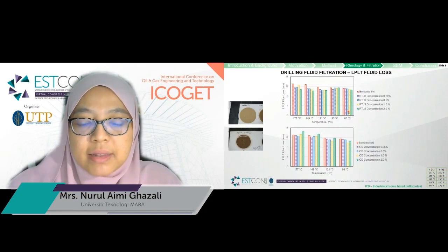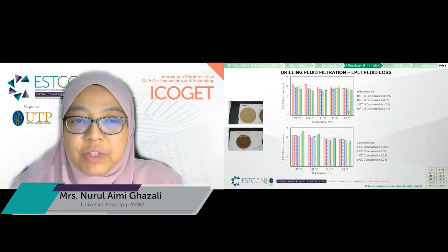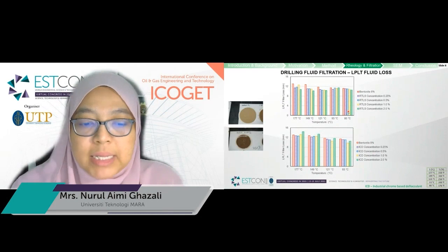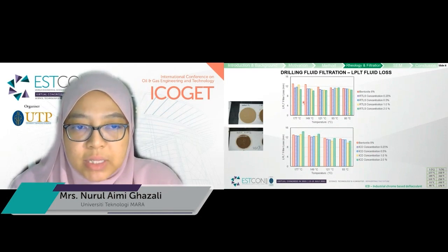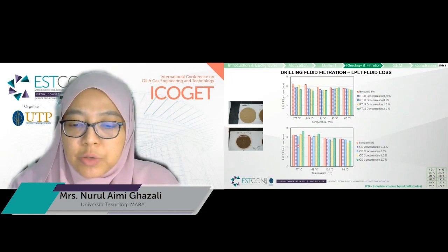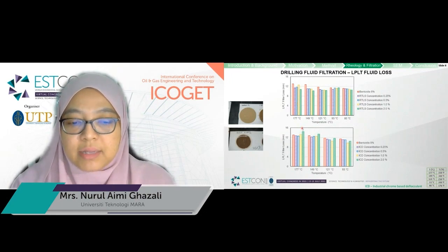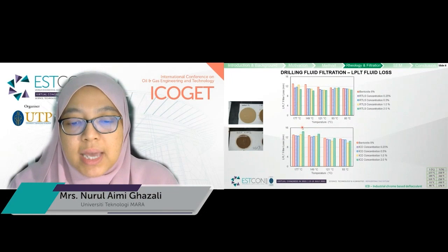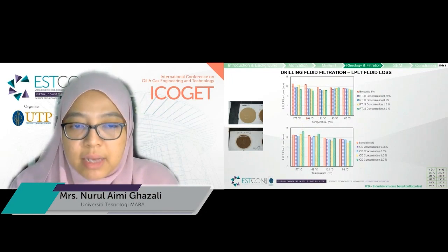A desired characteristic of filter cake, which is good for filtration, is thin and low permeability. At temperature 177, it looks like both RTLS and ICD can't reduce the thickness further, but it works at temperature 149 and below.